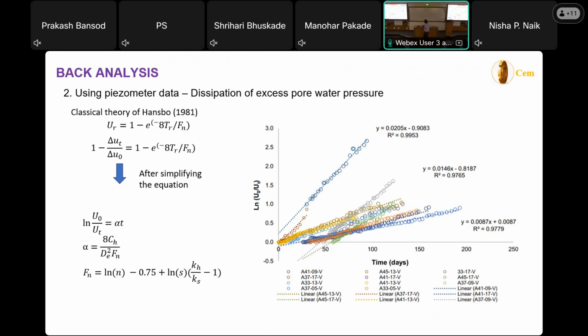Degree of consolidation happens due to the horizontal consolidation. With this, whatever we did, we have taken into consideration that there is no vertical consolidation happening, because the clay thickness is 15-20 meters. The vertical consolidation is very major because water has to travel almost 10 meters from the beginning, so consolidation is less. So we consider that vertical consolidation is not there, and horizontal consolidation is there.